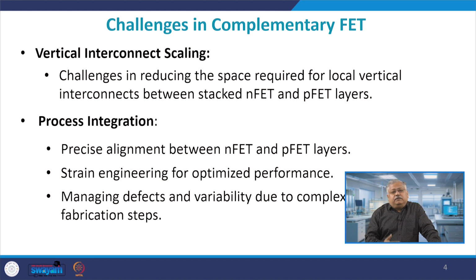The second one which people do in process integration is that they try to put in strain engineering. For example, silicon germanium stacking is done, right. When you do a silicon germanium stacking, that optimizes the performance because the mobility of the charge carriers becomes relatively very large in this case, right. The third problem in process integration is that you need to manage the defects and the traps properly. Because as I discussed with you in an earlier lecture series, the fabrication steps are not very easy.